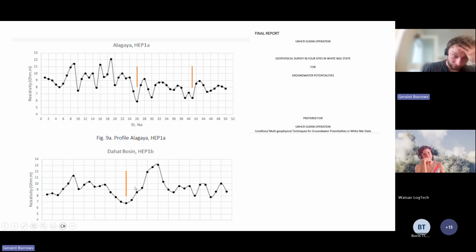Yeah. So I would say that this is a better signal. The lower one is a better signal than these ones. One of the rules of thumb is that these troughs that are being picked up within the constant separation traverse, if it's just one point at the base of the trough, there's less confidence in that as a signal compared to where you have more than one point at the base of the trough in this particular case. So that's a rule of thumb.